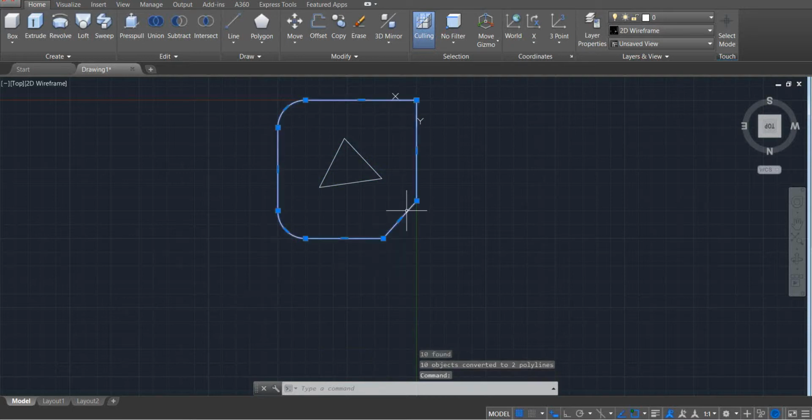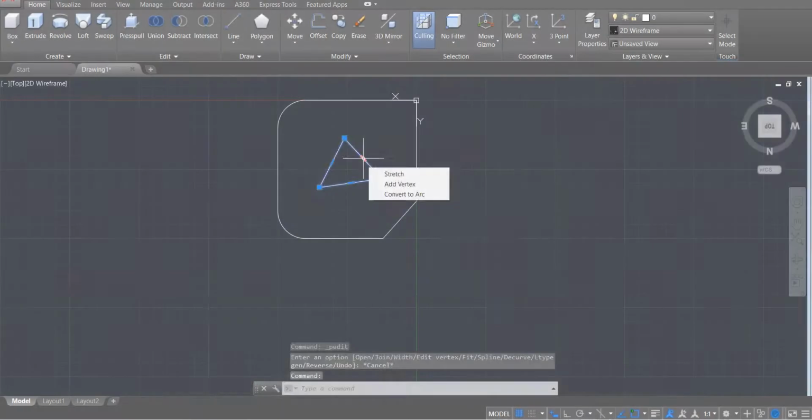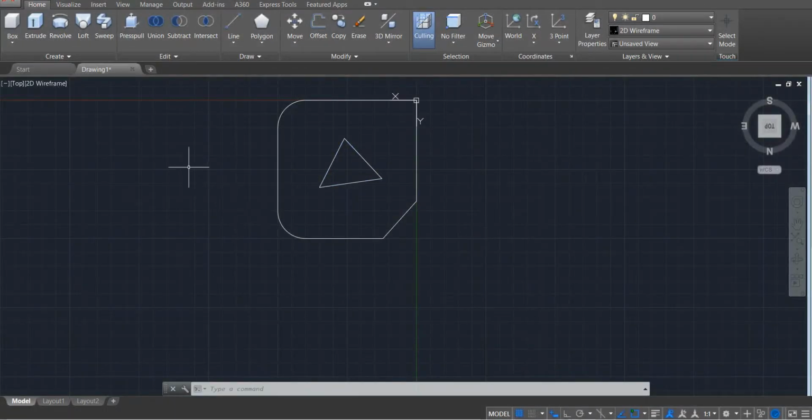This loop is a single loop, so when we extrude it, we're gonna end up with a standing solid object. And this is another loop. When we extrude it, we're gonna end up with another solid object. I'm gonna try to change the color. Forget about it for now, and let us just extend these two loops. As we mentioned, this is just two loops, so we can end up with two standing objects.